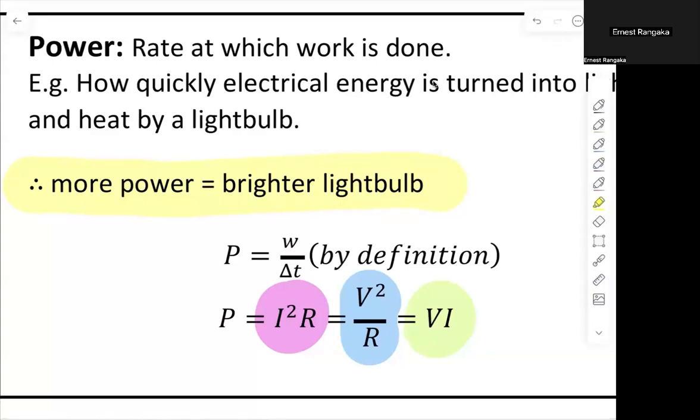How is the power output going to be affected? So look at how does the change in current or the change in voltage of the system change the power? If the power output of that particular device or light bulb or resistor goes up, then the brightness will go up. If the power of that goes down, then the brightness will go down. That's just a way to remember when they ask you, how does the brightness get affected? Think about how the power will get affected.